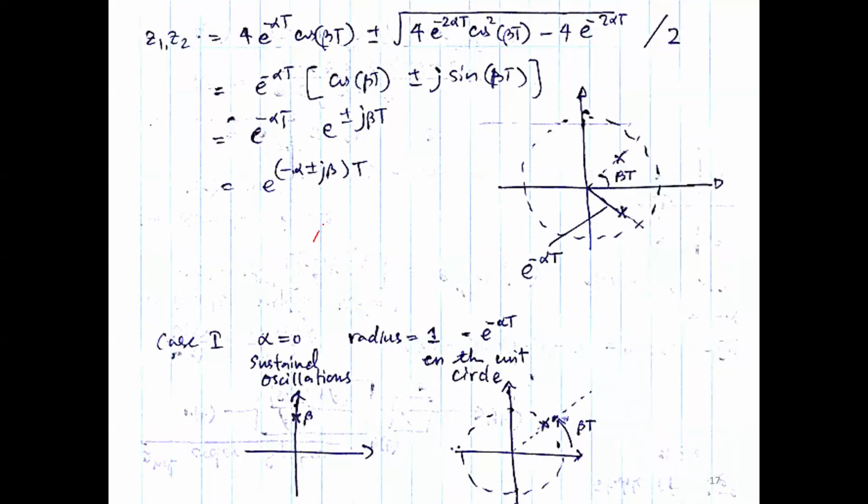If you just look at one sinusoidal waveform like that, if you want to capture this one, you need to take one sample over here and the other one over here. Wherever it is, doesn't matter. One in the first half plane, another one in the next half plane. So per cycle, you need to have at least two samples, which means your sampling rate has to be minimally twice the signal frequency. Okay.